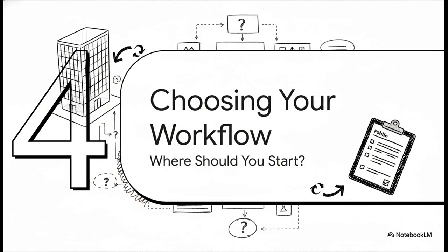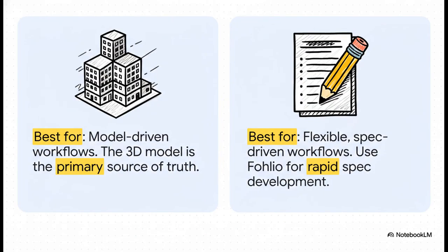So that brings up a big question. Which way is better? Should you start in Revit and export or start in Fohlio and import? The truth is, there's no single right answer. It really all depends on how your team likes to work. Here's the simple breakdown. If your 3D model is the absolute, unquestionable source of truth for your project, then you should start in Revit. But if your process is a bit more flexible and spec-driven, where you're constantly changing and updating product choices, starting in Fohlio is the way to go.